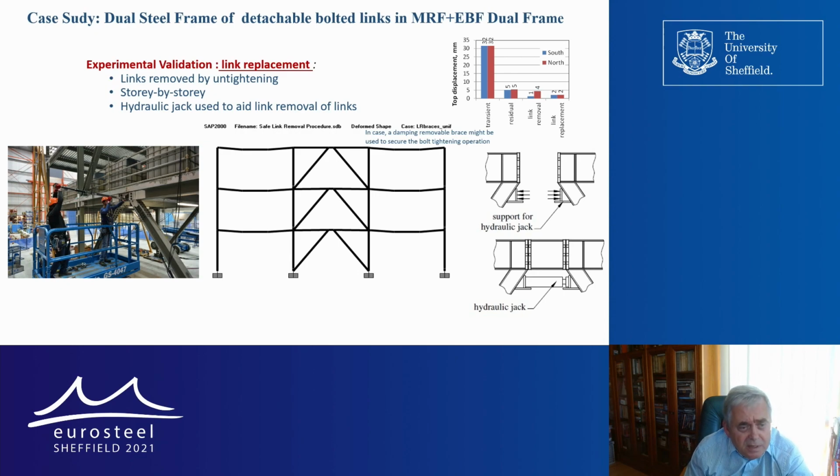And sometimes, if you have some larger deformation in the link, you must help remove the link by using some hydraulic jacks in order to extend the space a little and to extract the link after untightening the connection.